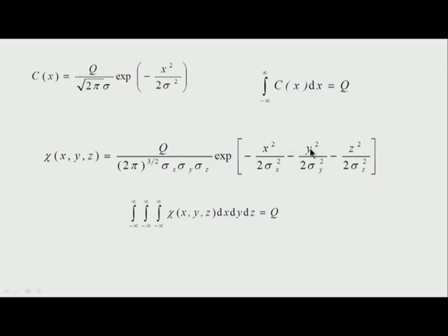I have now the diffusion taking place in y, that is, in the lateral direction, or let us say this is the x direction, and in the y direction I have diffusion taking place. Therefore along y I have sigma y over here, which is the standard deviation in the y direction. I also have z squared corresponding to the vertical direction, 2 sigma z squared. Well, this is what the value of concentration should be.